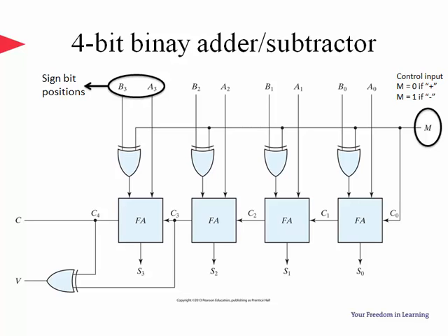This slide is basically showing us that the same hardware circuit can be used to implement both binary addition and subtraction. It is, of course, left as an exercise to draw the same adder and subtractor circuit using the carry look-ahead logic. It should be possible. The control input you can see on the top right of this slide, M, is used to select the addition or the subtraction operation by setting M equal to 0 or 1.